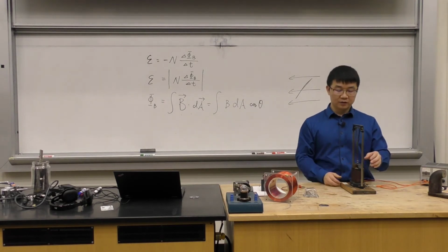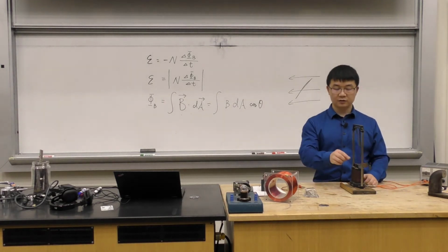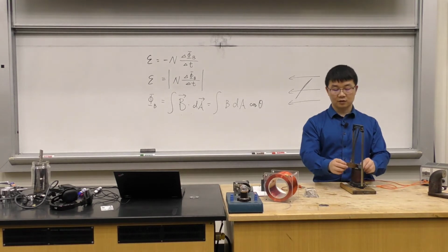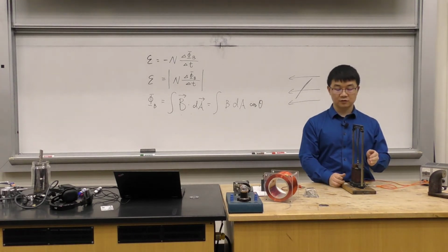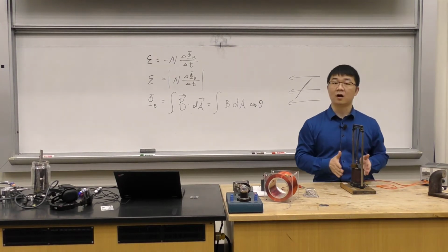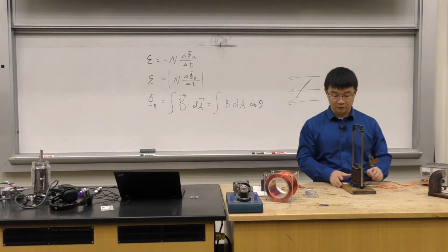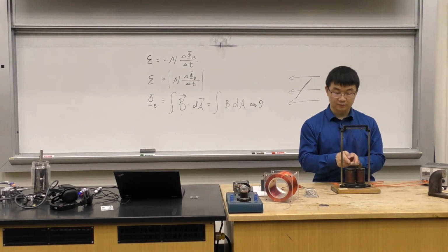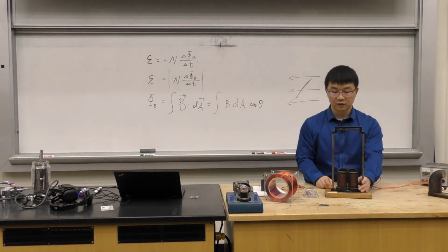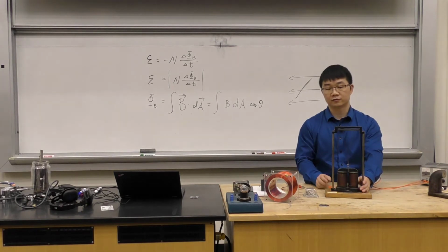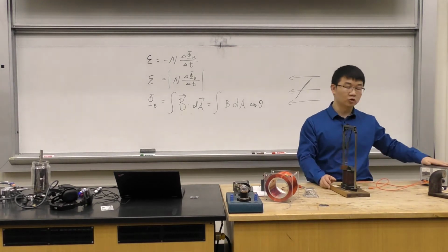So that's why once there's an eddy current, once there are induced currents caused by the relative movement between this conductor and the magnetic field, the induced currents are always going to slow down the motion, even though they're not in contact. There's a gap here. I don't know if you can see that. You can now see it's going to swing very freely because I haven't turned this on.